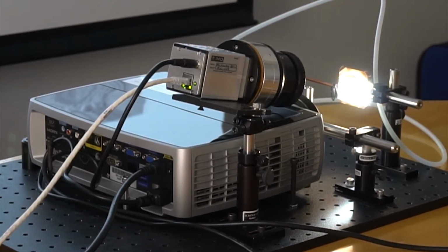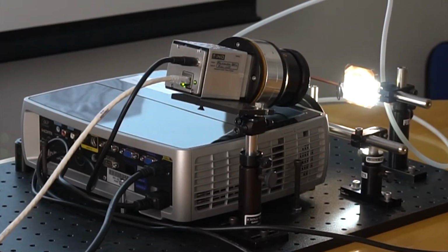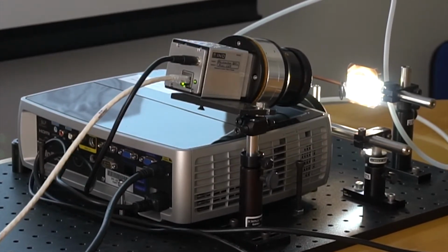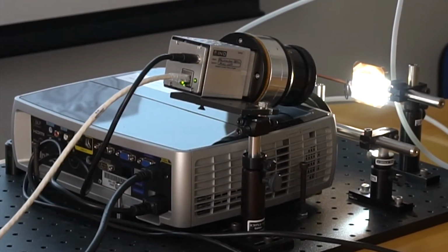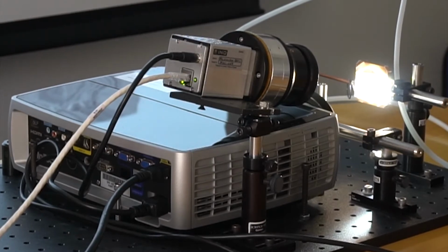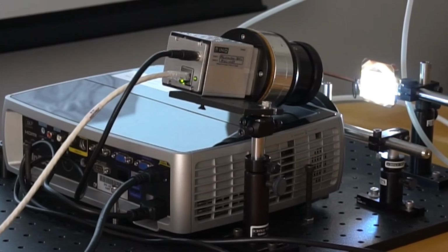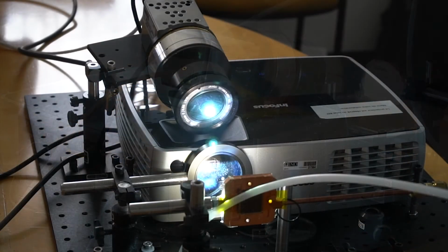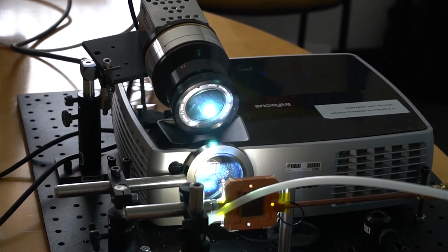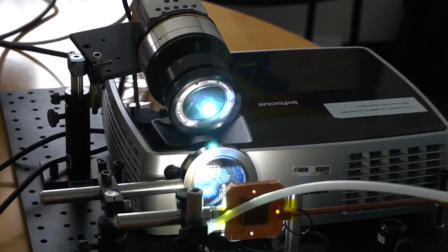It is also possible to use other light sources. You can imagine using a laser which would shine on the chip, again on the same principle, and would hit individual pixels. The pixels would start to radiate infrared radiation, and the device under test, a camera, could actually capture this radiation. We can also imagine that we would use multiple sources, such as a visible projector combined with a laser, or combined with multiple lasers.